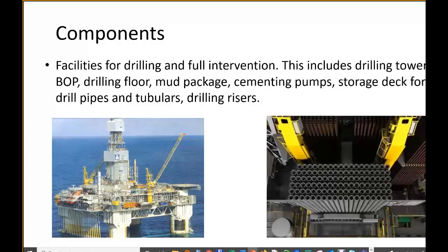So if your offshore structure has these facilities, that's a big thing. Okay? It requires a significant amount of space, it's expensive, and we will see now it also depends on the capacity of that drilling rig. Okay, if you want to drill deviated wells that are extended reach, very far away, then you're going to need quite a robust and big offshore drilling package, which is going to make the structure also heavy. Okay, also heavy and more expensive.